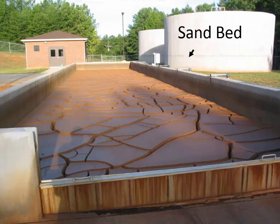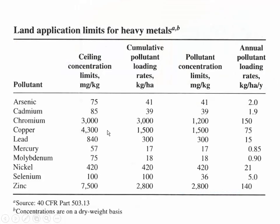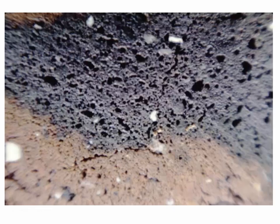If we are dewatering it, we have to be mindful of the fact that there are limits on the heavy metals that can be applied to land. If you're spreading it out over an agricultural field, there are environmental rules that say how much chromium, how much copper, how much lead is allowed to be in sludge solids.